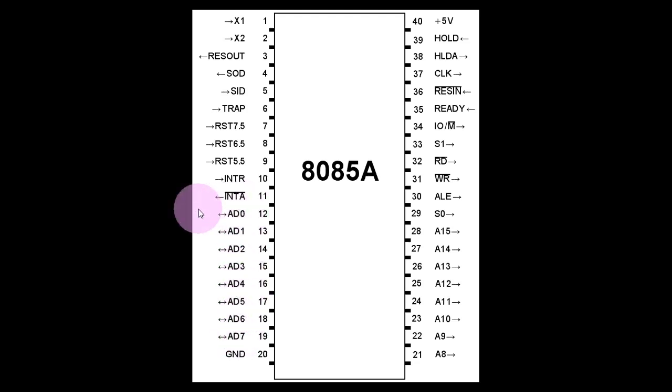But for address, it will only transfer outside the microprocessor, because if the microprocessor wants to read memory, it will pass its address through these address lines, from AD0 to AD15, to the externally interfaced memory. Once the address is passed there, it will try to read the data, so it needs to take back the data through these lines. Now, there is a problem. How does the external device know at what time the address is available on lines AD0 to AD7?